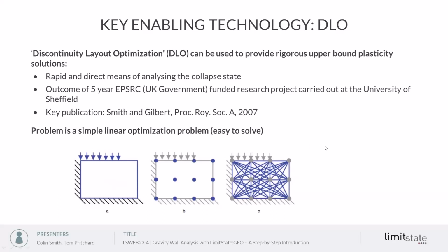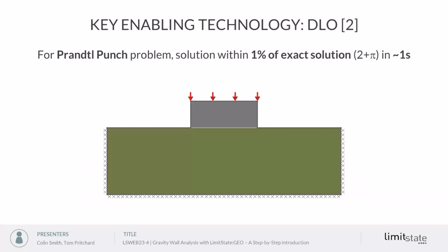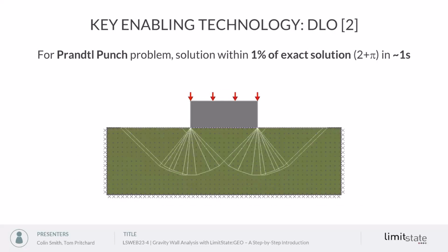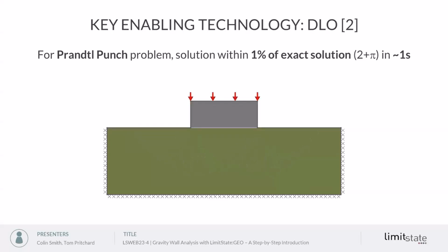And then we use optimization to pick out of those the slip lines that give a mechanism that dissipates the least energy. And that's the one that's going to be critical. In this problem, we've got 12 nodes. Typically, we'll be using 1,000, 2,000 nodes and millions of potential slip lines to solve. And this gives us a really flexible way of generating slipline mechanisms. Just to illustrate one example here in terms of a foundation, we can very rapidly get to the classic pyramidal mechanism here.